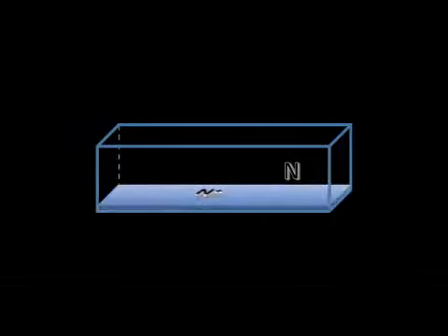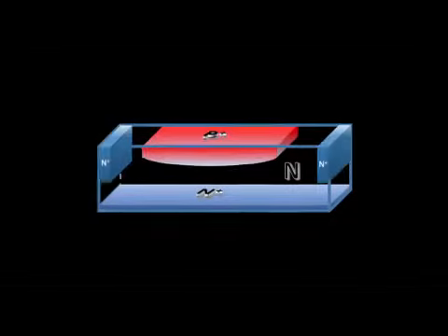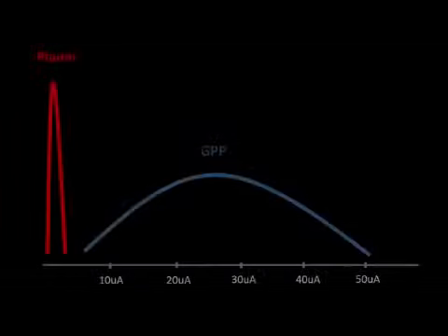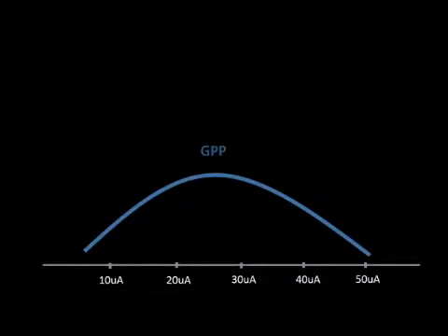Planar process with the uniformity of electrical field of the terminal ring for stabilizing the withstand voltage of the diode, which means lower leakage at the same reverse voltage compared to GPP. Planar sustains higher junction temperature. Lower forward drop.